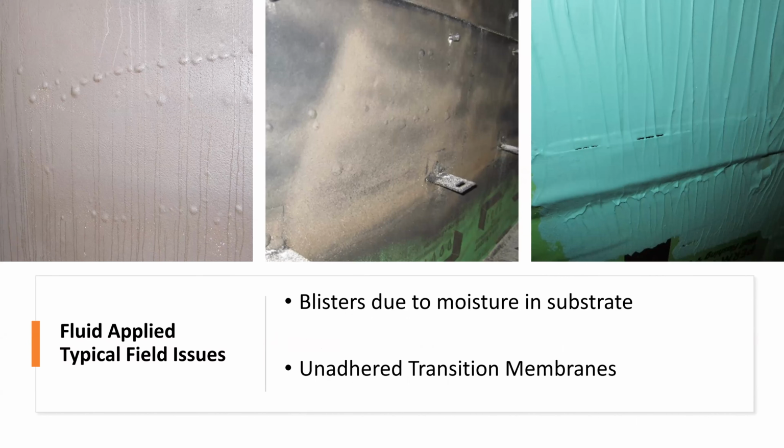So here is what might happen if you have moisture in the substrate. We've put our air barrier on, we've trapped some moisture in there, we've kind of made a pool. Like we've put this membrane on, it's like a pool liner. Now that moisture is in the substrate, we've got the sun beating down on this black membrane, and that substrate starts to dry out.